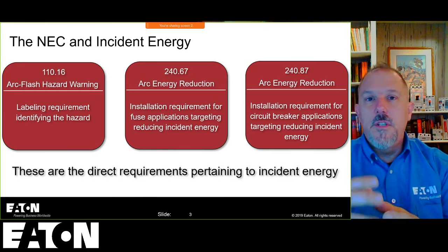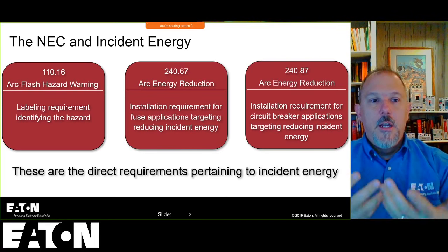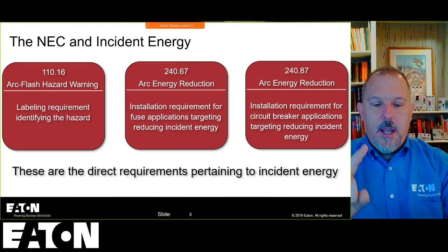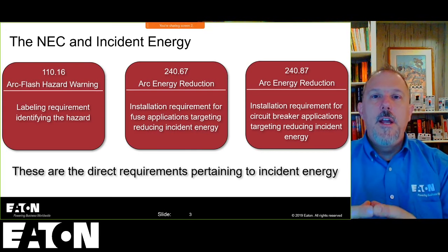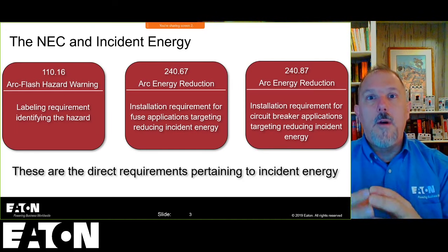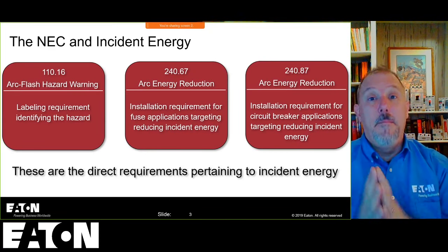This was even before Ralph Lee's paper that we got into arc flash. So we had all of this going on, and then we had Westinghouse, and you had GE and a few others. I think Westinghouse was the first one to come out with the ground fault protection of equipment in their breakers, and that just basically opened the doors up. And then you had requirements now in the code for that equipment at service entrance, and really it hasn't changed since 1970 all that much.